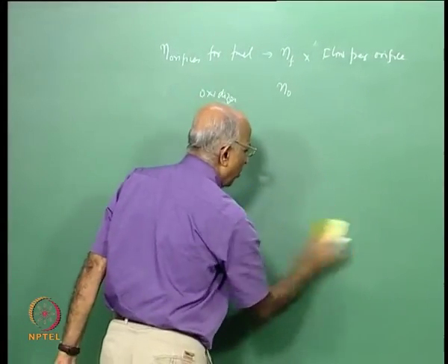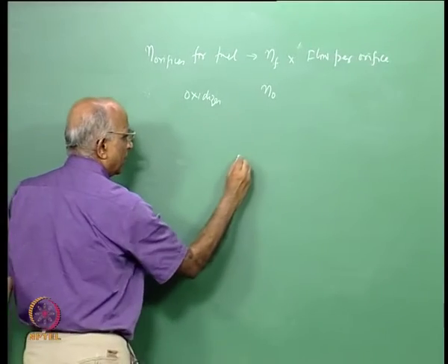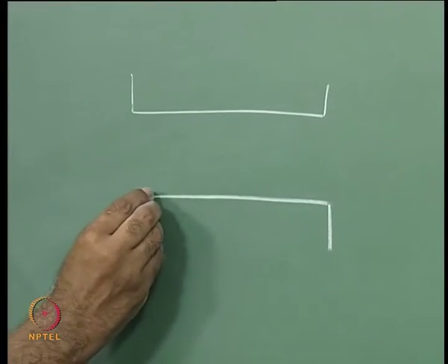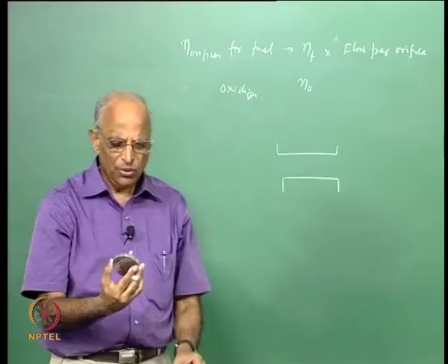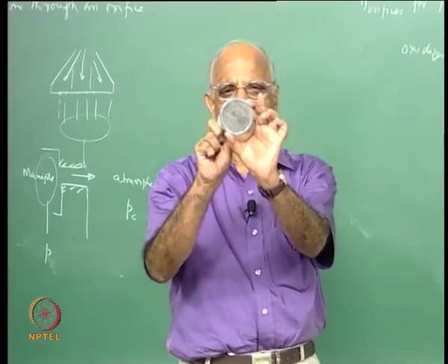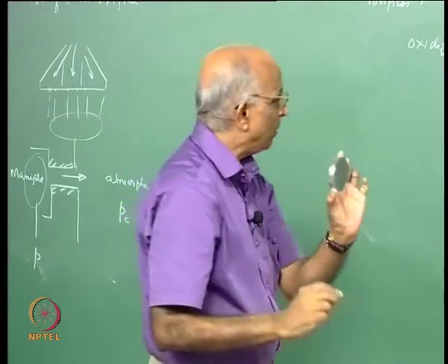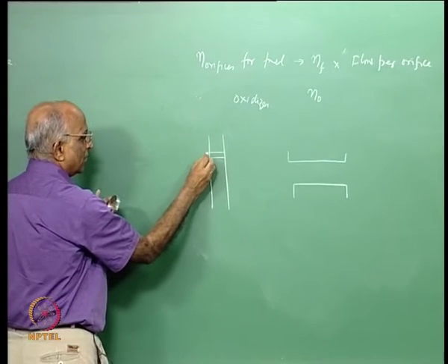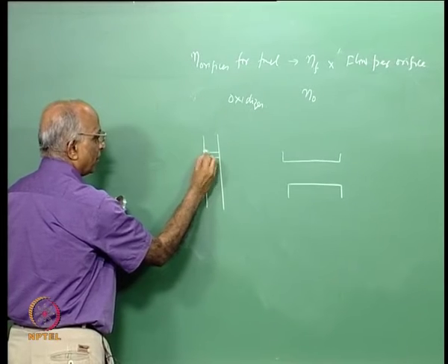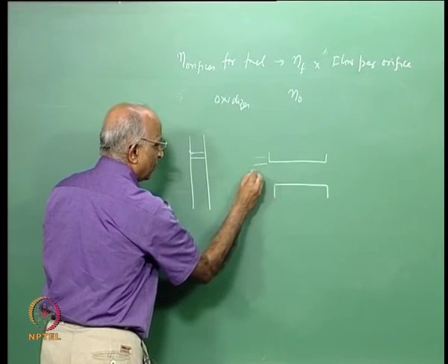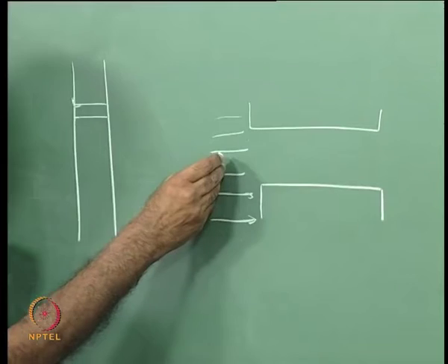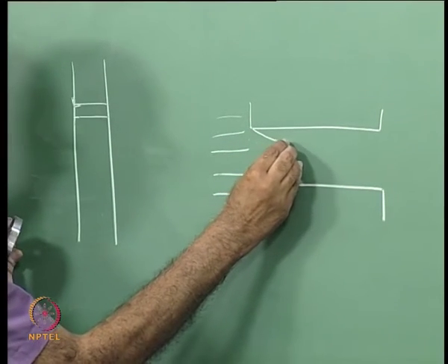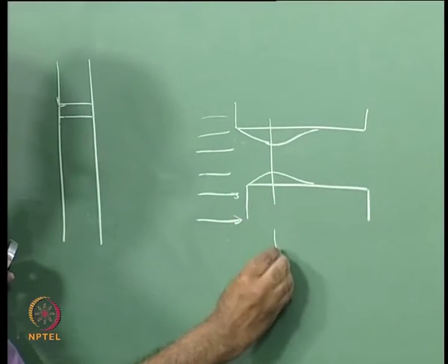I find there are a lot of things even in a small orifice flow which we need to understand. The thing is that I have an orifice like this. Most of the orifices are sharp edged. How do I make an orifice? If you take this particular showerhead, you find yes, this has something like 30 or 40 holes in it, but each of the holes is just drilled. When I drill a hole in a plate, I take a plate like this, I drill a hole like this, I remove the burrs here, that means it is a sharp edge over here, the edge is very sharp. That means the edge through which the liquid enters from the manifold like this, it has high pressure here, almost 0 velocity, and when it enters it contracts to a minimum over here and then reattaches over here. This we call the vena contracta, right.